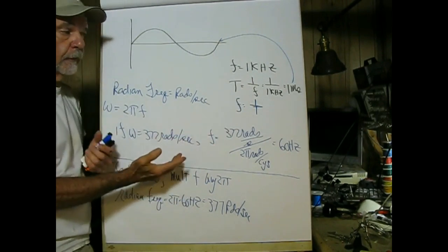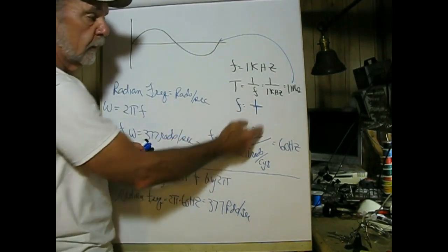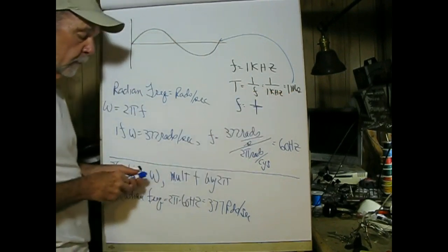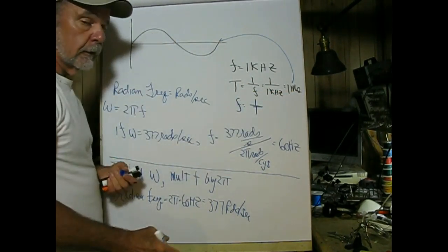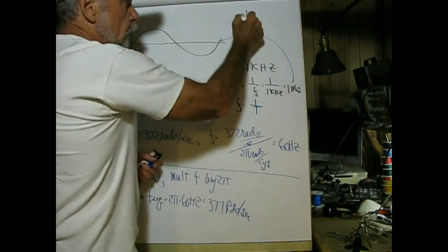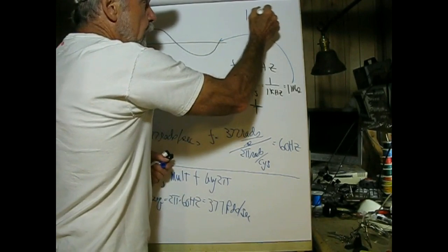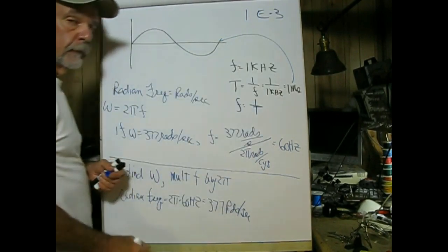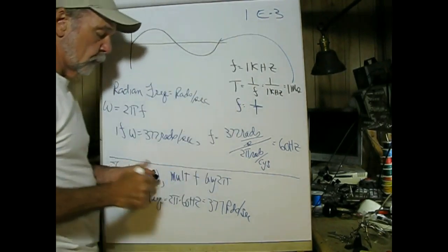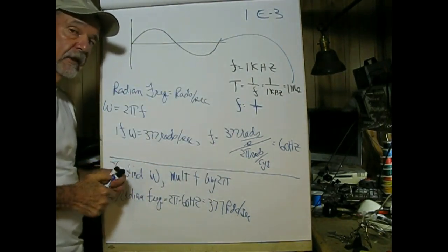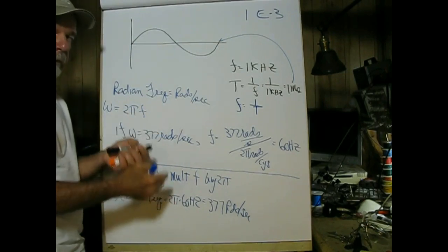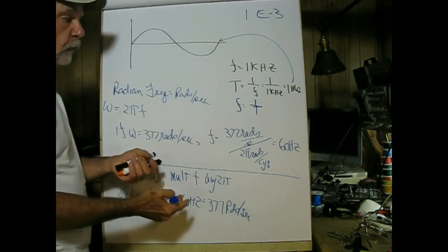So the period for a 1 kilohertz sine wave is 1 divided by 1k, and that'll come out to be 1 millisecond, which on your calculators, which should be in engineering notation mode, would illustrate that as 1e negative 3. And that's the power of engineering notation, because it'll always give you an exponent which can be evenly divisible by 3, meaning milli, micro, nano, pico, and so forth.